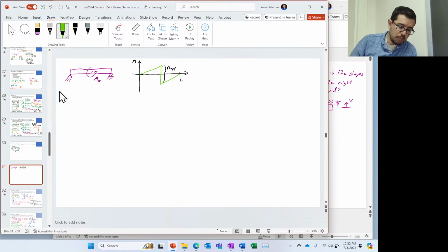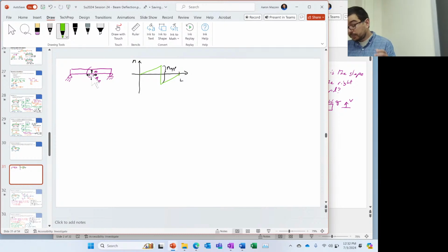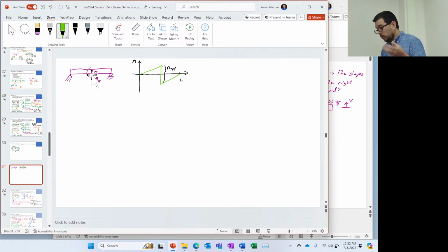Okay, and the actual line or lines, they're constant slope. There's no shear. There's no distributed load, which means that the integral of that is going to be a constant. So the shear force is just going to be a constant, and the integral of a constant is then a sloped line. The way I did it, I just did it with the reaction forces, and then with the external equilibrium. So on the left hand, had F1 going up.